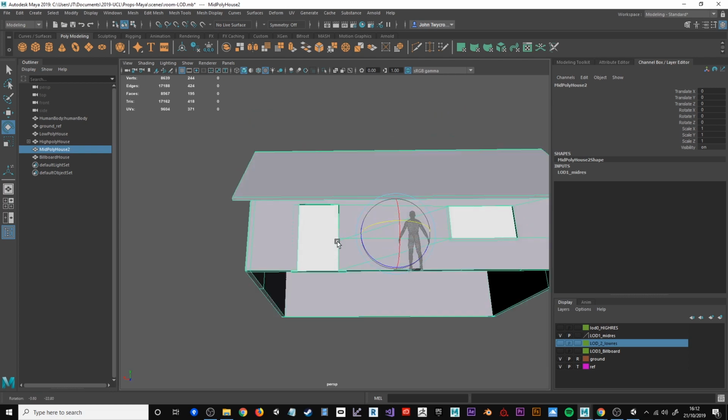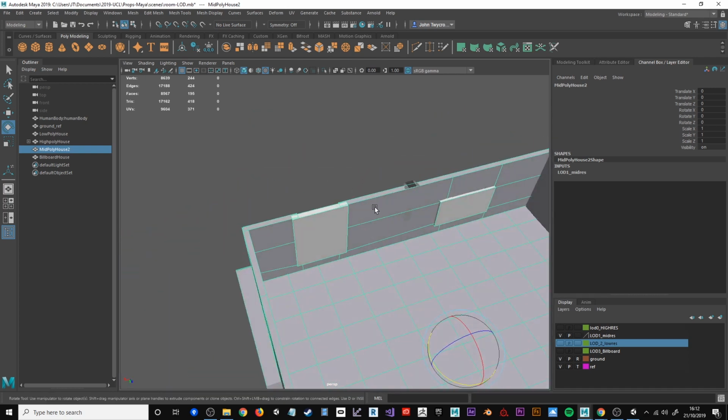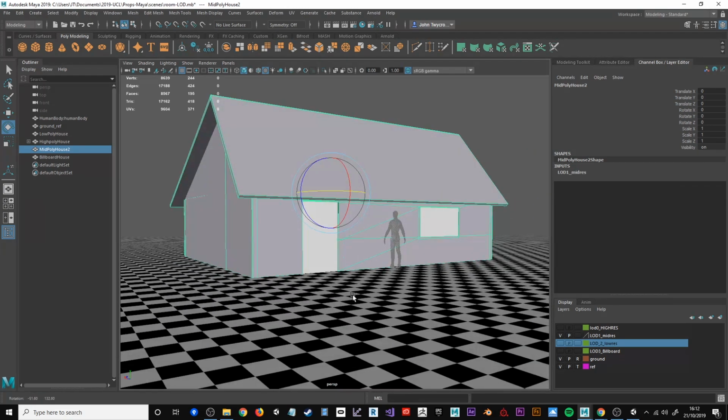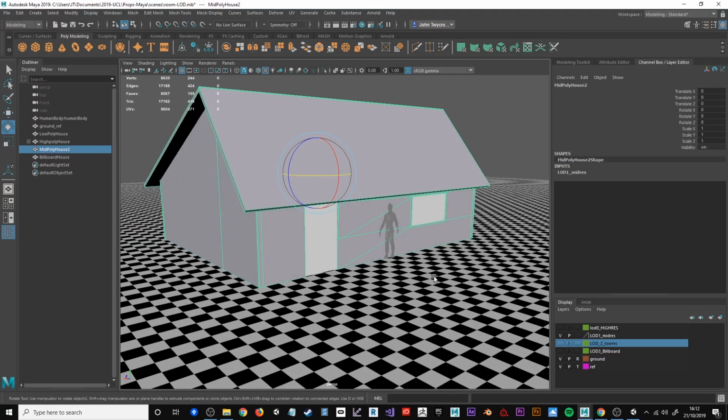I could in fact reduce this more because I have inside faces on these. I made these out of cubes so I could have inside faces, so you could actually walk into the building, but that's not 100% necessary in this. So I could clean that up and take some of those away. If you're not inside the building, you won't need to see those. So I could probably halve that again. I could probably get this down to 140 or 120, and that again will help the rendering.